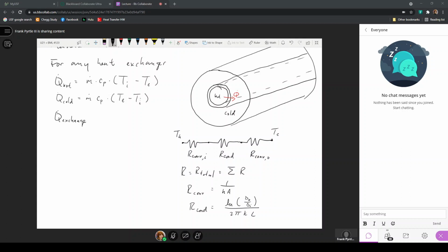This heat transfer coefficient will be changing until we get to a thermally fully developed condition. So for this expression of the resistance due to convection, if the heat transfer coefficient approaches infinity at the very beginning of the pipe and gets smaller, it says that this resistance due to convection is going to increase as we move along the length until h becomes a constant.